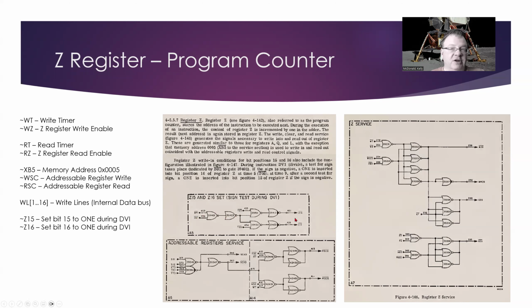And the answer is thankfully no. A lot of this kind of logic here is implemented as part of the generation of various control pulses. So as we go through and look in more detail at the sub instructions and how they're executed, the execution of the divide instruction will make these branch checks and assert the appropriate control signal for the register to behave appropriately.